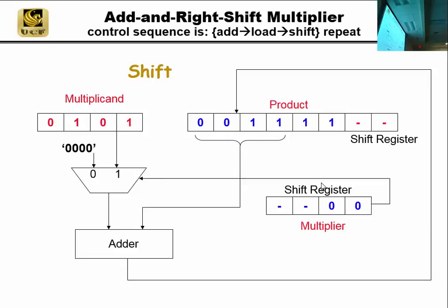So now you have a 0 in this digit. You're going to add 0 to what? This upper 4 bit. Adder. 0 plus 3 is 3. Next clock cycle comes, it's time to load. 3 gets loaded. Time to shift. Now we got this digit of 0, the same thing as last time. We're going to add 0 to this value, it's just itself. Time to load. We did the add, now time to load. Time to shift. Okay. It's the last step.